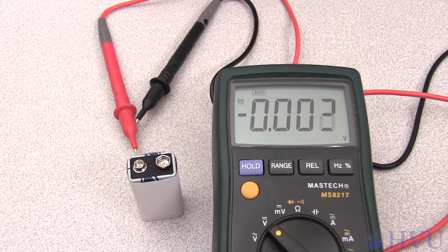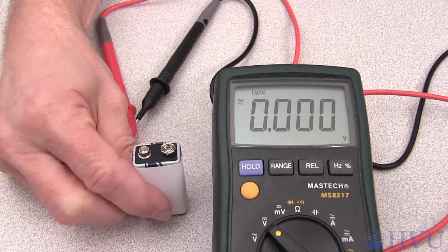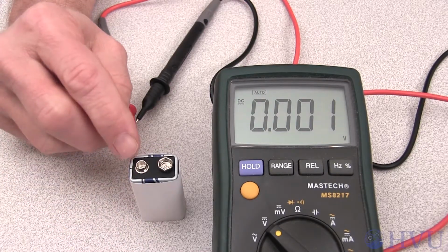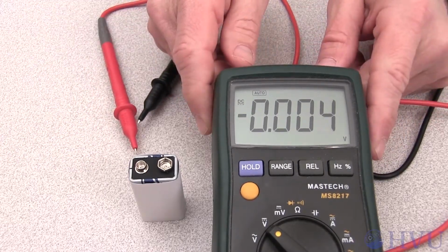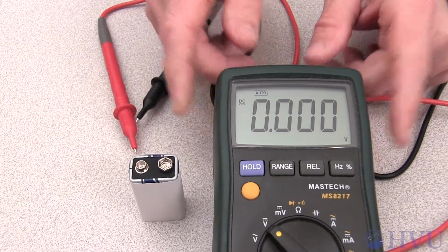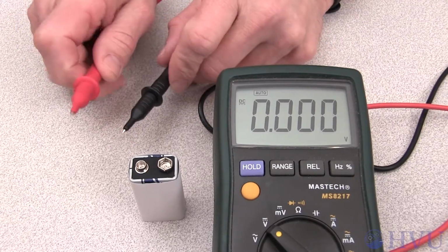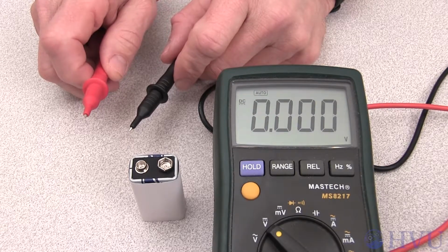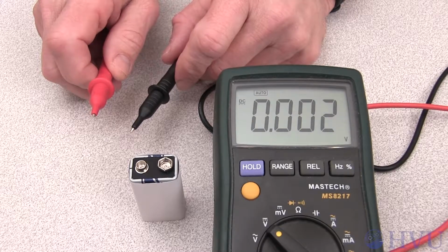This can also be illustrated with a quick measurement. I have a battery which should provide about a 9 volt difference between its terminals, with this terminal being the higher voltage. I can measure the voltage difference with this digital multimeter, or DMM. The DMM displays the voltage difference between its red and black terminals, with the red terminal being assumed to be the higher voltage. This corresponds to setting a sign convention on my measured voltage.